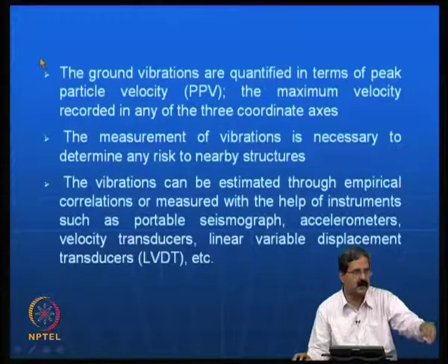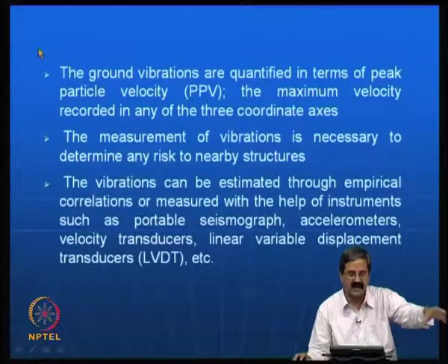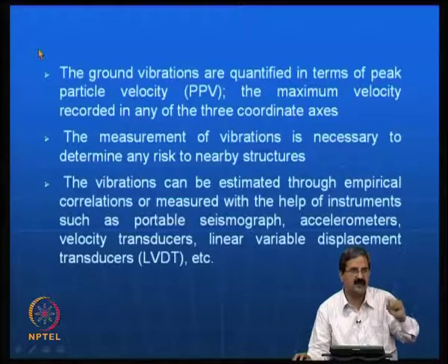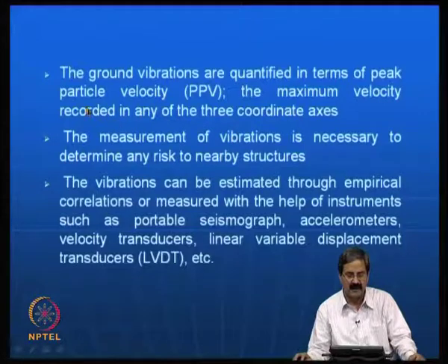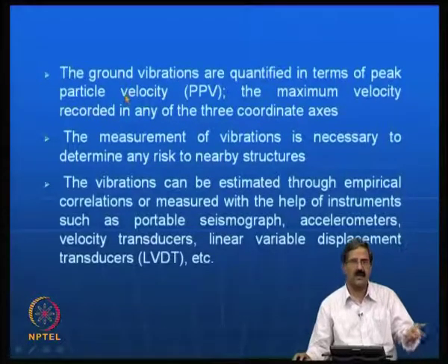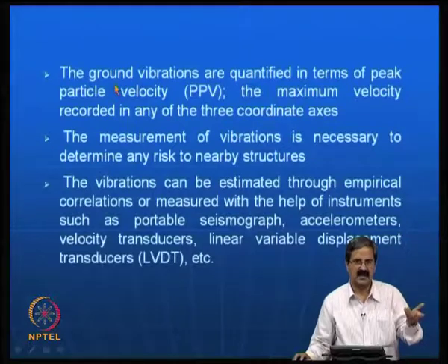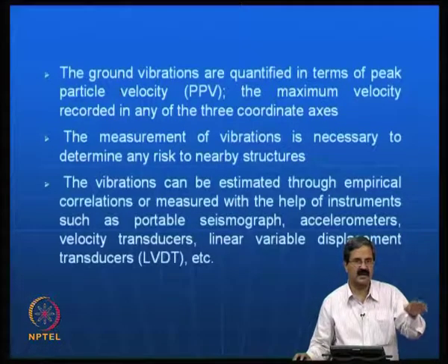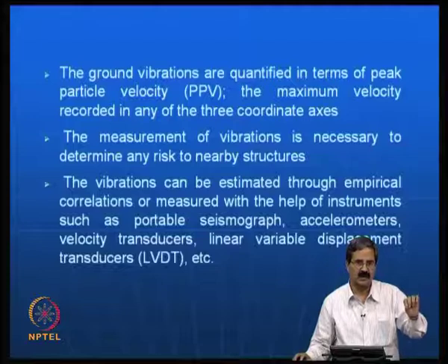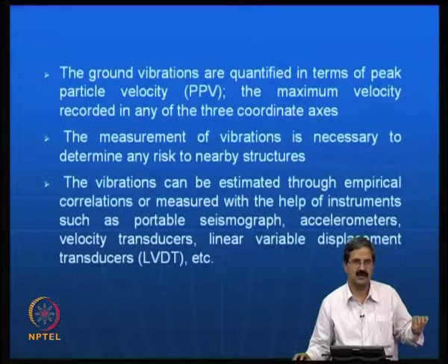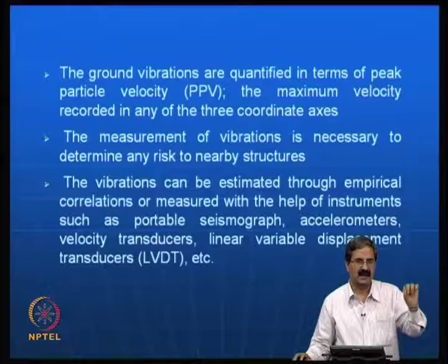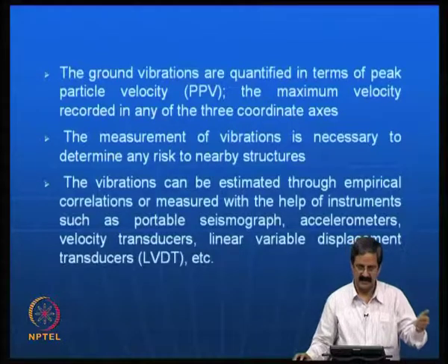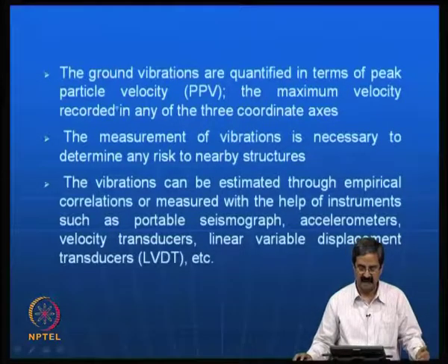You can use pickups here and there and pick up the velocity of the particle that is traveling. The maximum velocity is recorded. If you put accelerometers, from accelerometers you can get velocities and displacements also. It will have 3 components, x, y, z.